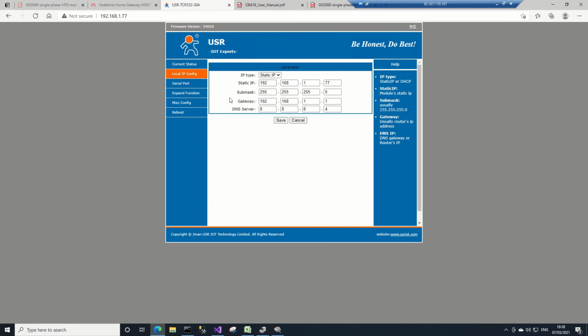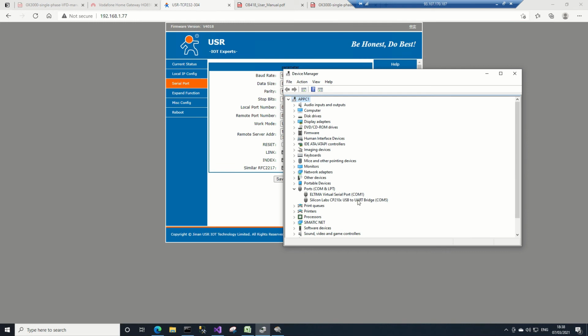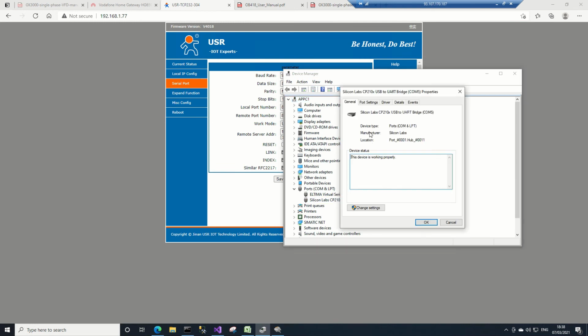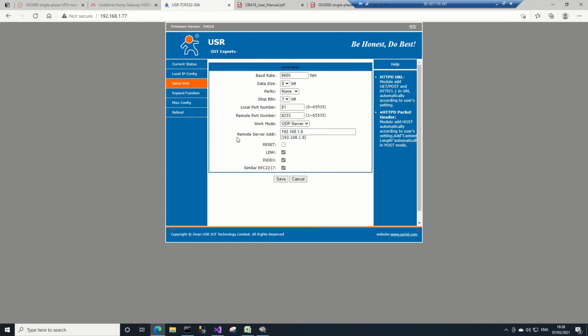One side is the part that connects to your standard network, and the other side is where you're configuring an RS485 port in the standard sense. What you have to do is make sure that all of the settings that you would normally set for other COM ports, you actually set them on the Modbus or Ethernet RS485 converter. And this is really, really important.